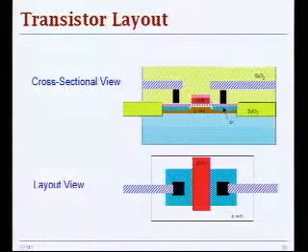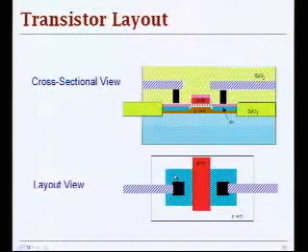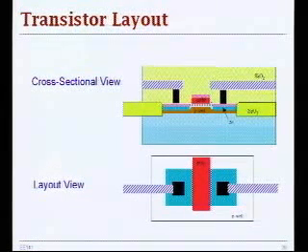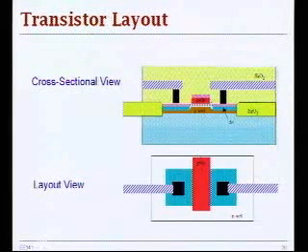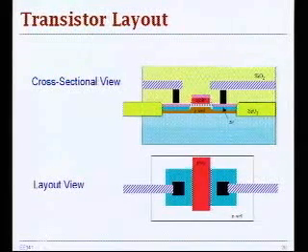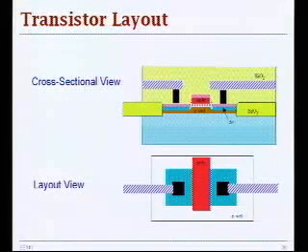You can put either first poly and then you can put active on top of it, or you can put active and then poly. It doesn't matter in which sequence you do it. It's important that you understand how this works and to be able to define a proper set of these rectangular objects, because your layout is a set of rectangles that are attached to certain manufacturing layers. And that's what you're going to do in your labs when you create layout.